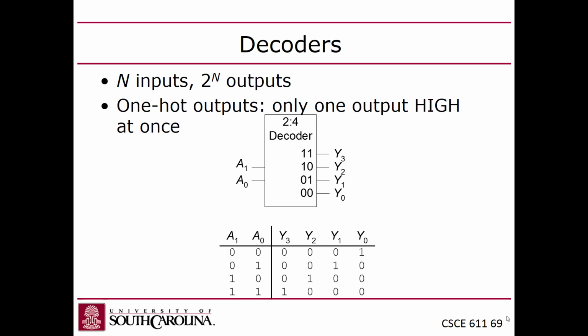Now, what's so great about the decoders? I remember when I learned about this, I was like, okay, that's neat, but who would ever use that? What is that useful for? Well, it turns out that decoders are used in every computer memory there is. They are the fundamental basis by which all computer memory, DRAM, SRAM, flash RAM, all of them, use a decoder, because the memory address goes in and you've got a set of wires that come out that activate a memory cell for reading or writing.